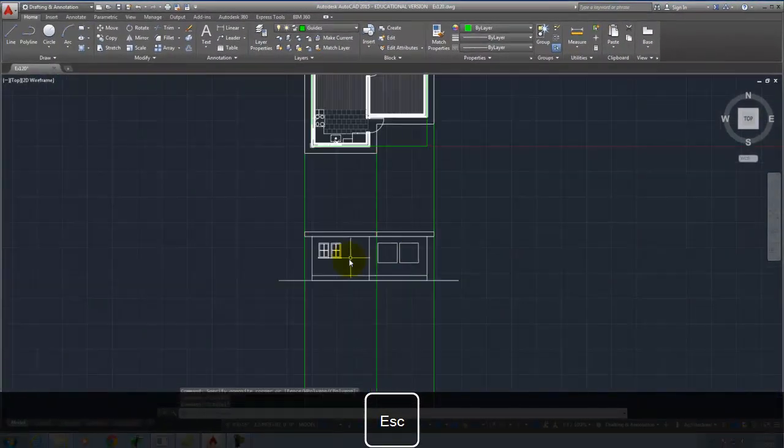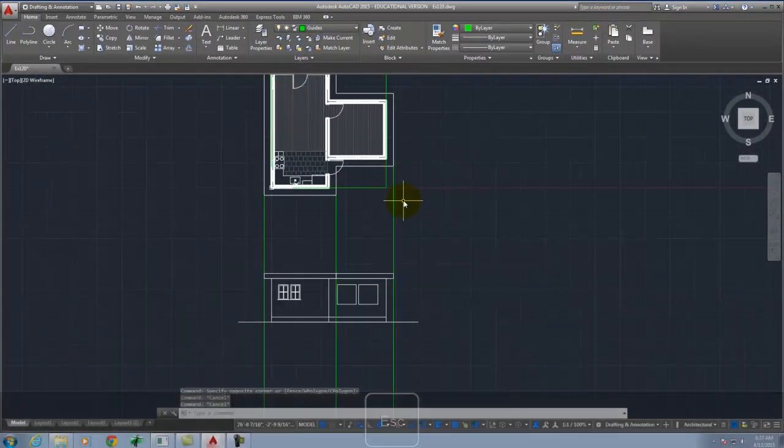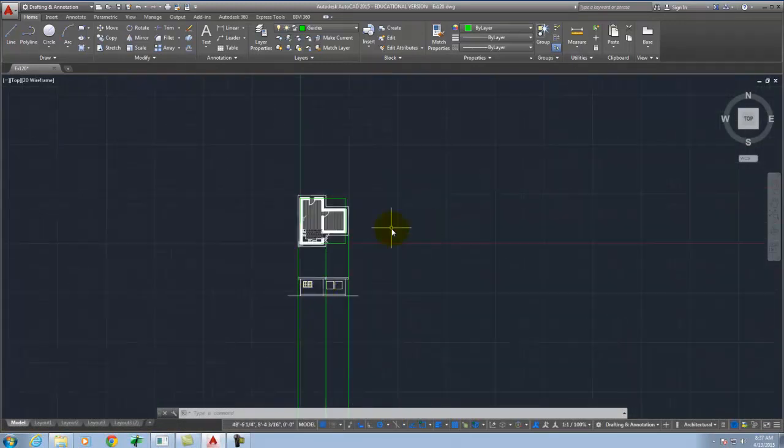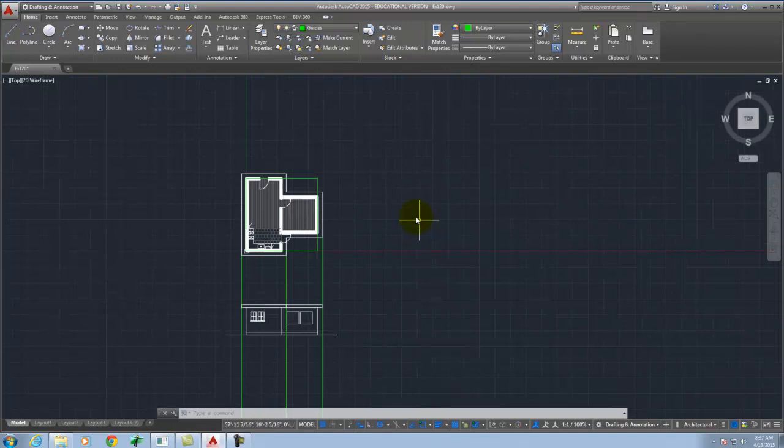All right. So this takes a little bit of mental work, but we can draw the east elevation right over here. And we can reference this line very easily using what's called a 45-degree reflection line. So those of you that have been in 130 before, this makes sense, right? It works the same in AutoCAD.